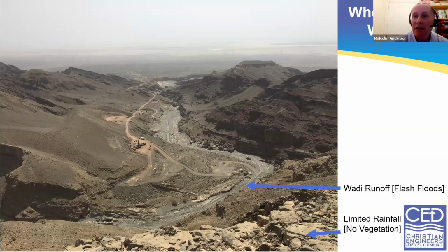The nature here is that basically you'll get a flash flood and that'll be enough to move boulders the size of a double-decker bus. It'll certainly sweep away anything in its path. And then you'll get a tail to that runoff for about a week, in which the groundwater in the sands and gravels in the bottom here drains down. But then that'll be it for the next 3 to 4 months. So the wadi runoff isn't really a solution because you've got to build a big dam, and that's far too expensive.